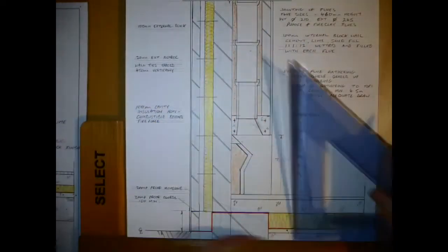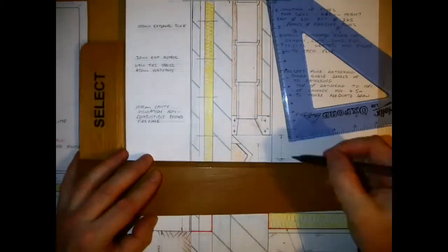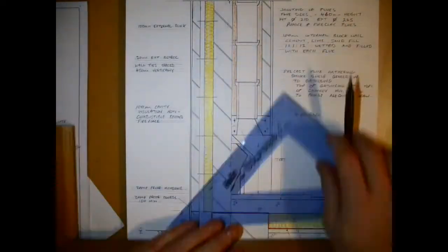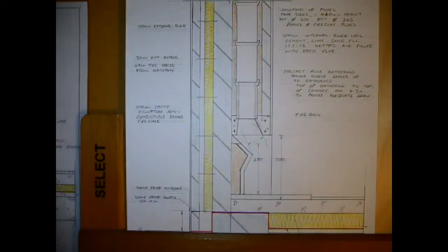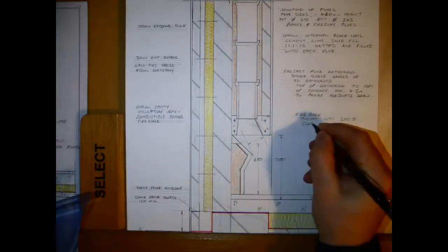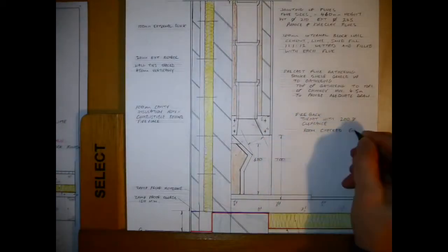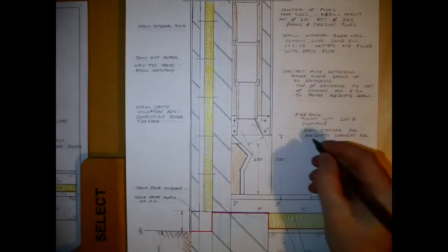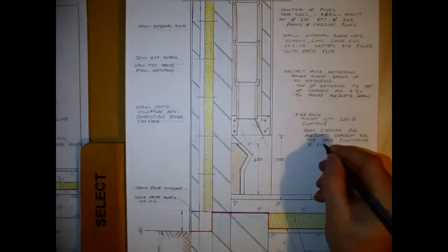Heights and sizes around the fireplace here, I've put in at 700, that'll be a max size, and 600 millimeters roughly to the top of the fire back. I think it's about 610 in actuality, and the throat here just showing that it's got adequate clearance from where the combustion takes place.